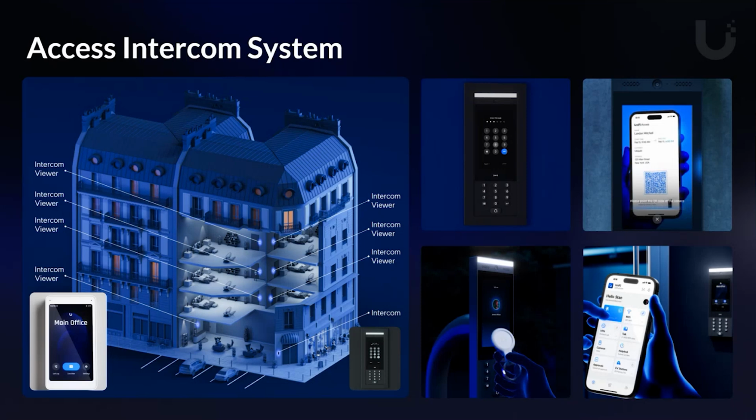You can have it set up to where there's an intercom unit installed at the door at each external entry point, and then you would have that connected to a hub that then connects to the lock. It connects to a chime if you want to. It connects to the emergency alarm panel so that when there's an alarm, it automatically sets it to open. There are also several other connections on the hub, but you would connect this intercom to that hub, and then connect to the lock.